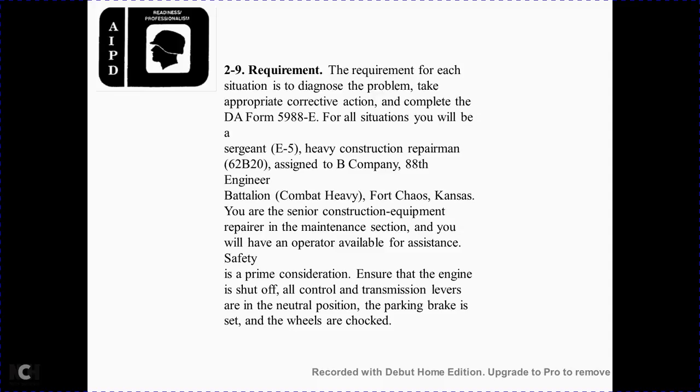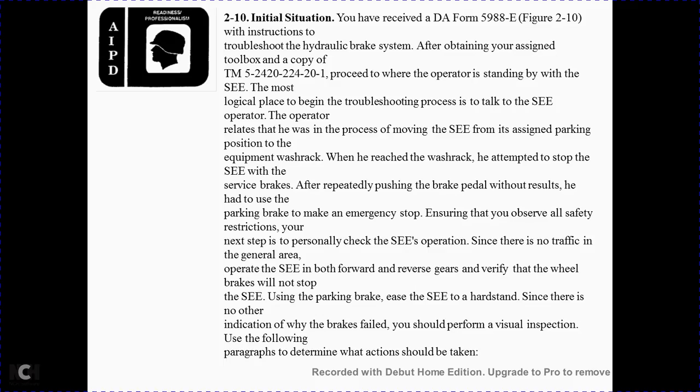For the situation review, you will be a sergeant, heavy construction repairman assigned to B Company, 80th Engineer Battalion, Combat Heavy, Fort Leavenworth, Kansas. The senior construction equipment repairer from the maintenance section will have the operator available for assistance. Safety is the primary consideration. Ensure the engine is shut off, all control transmission levers are in neutral position, the parking brakes are set, and the wheels are chocked.